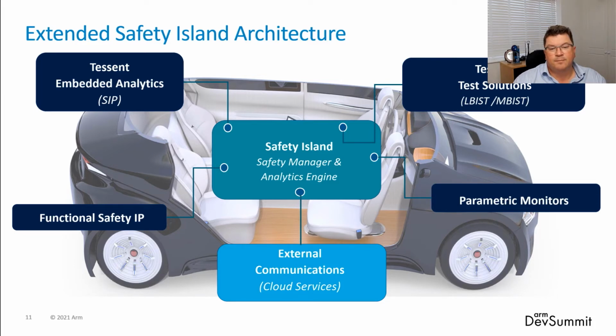So in the reference architecture, I talked about just straightforward test instruments. However, once you have the safety island implementation done, it's very easy to extend this into other technologies that you can embed in your device to help with the collection of health and reliability data. For example, the connection to the safety island could be extended to things like the functional safety IP, to monitor the various flags that get raised from that functional safety IP. You could also connect it up to the test and embedded analytics IP, which will be running in functional mode, collecting performance, safety and security data based on the functional content of your design. Also, if you embed various parametric monitors into the device, we are also able to collect the data from those as well using the safety island application.